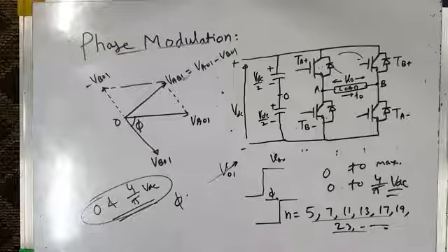We have also seen how we can choose the locus of PWM technique on the switching angle plane such that V5 by 5 minus V7 by 7, this difference, is kept very close to 0 in order to minimize the pulsating torque. And similarly, we can find the switching angle combinations in such a way that overall losses are reduced.